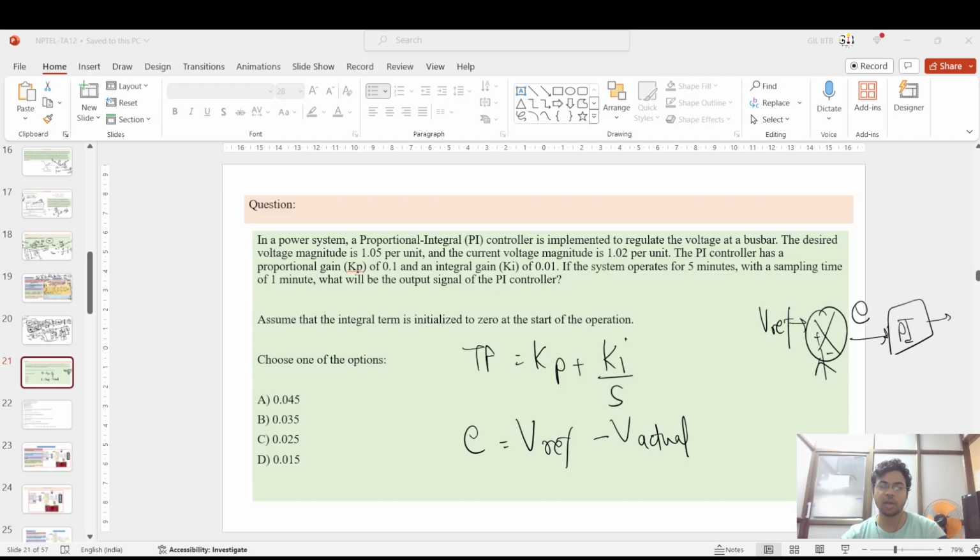No, no, no. Actually, IL is being generated based upon your generation. Suppose that you have a PV generation and it is at a 1000 irradiance level. So the current will be higher at that irradiance. Suppose the irradiance lowers to 500 watt per meter square, then the current will reduce. So based upon the generation capacity of the DC sources, this IL will differ.